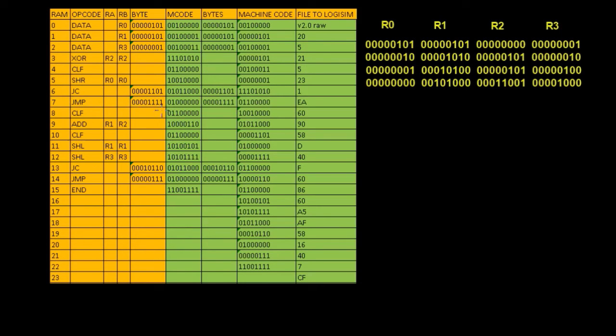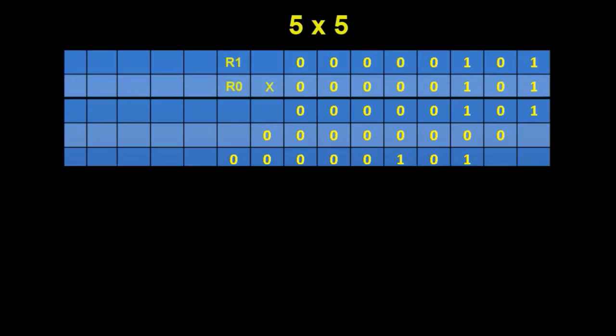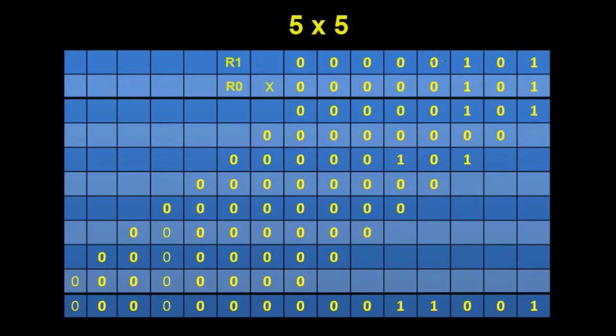So this point here is going to be 1, 2, 4, 8, 12. So this point here is actually just one beyond the add instruction, because we don't need to add anything on here because it's just a value of 0. So it just jumps to this line here and it clears the flag, and then again it shifts the value on register R1 to the left. So it shifts this here again to the left. Shifting to the left again is like multiplying by 2. It's equivalent to moving along here in our most significant bits whenever you do the normal multiplication.